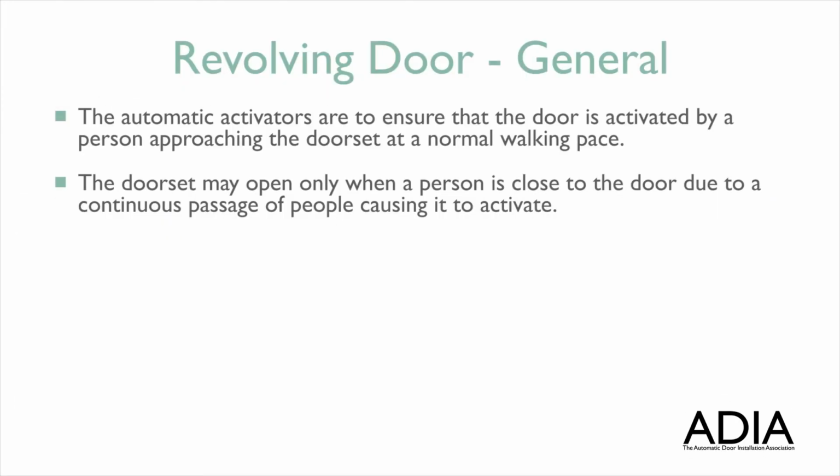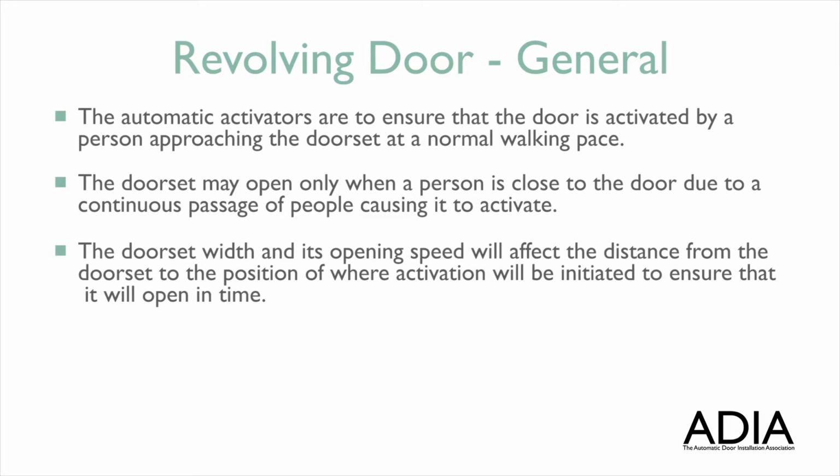The door set may open only when a person is close to the door, due to a continuous passage of people causing it to activate. The door set width and its opening speed will affect the distance from the door set to the position where activation will be initiated, to ensure that it will open in time.